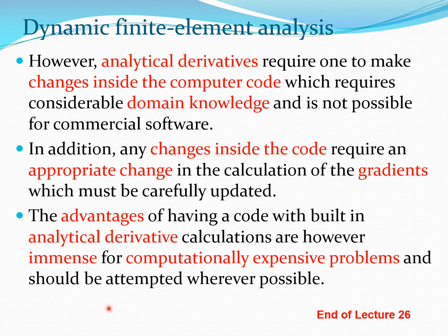For example, if you are dealing with robust design or reliability based design methods where you may need to call your function an enormous number of times to do a Monte Carlo simulation to get estimates on the statistics of the objective function and constraints, in those cases it's very useful to use sensitivity derivatives if you can.